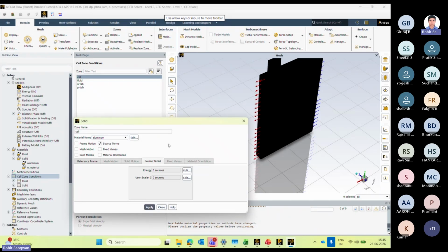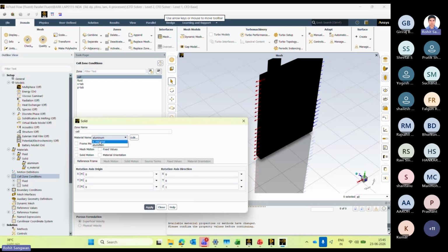But the battery model gives more accuracy compared to a heat source. Mostly we have observed that a lot of researchers use this source term instead of the battery model. That source term we generally use in the PCM model when we are using solidification and melting. Whereas for the cooling part, we should go with the basic default, with the help of the battery model.